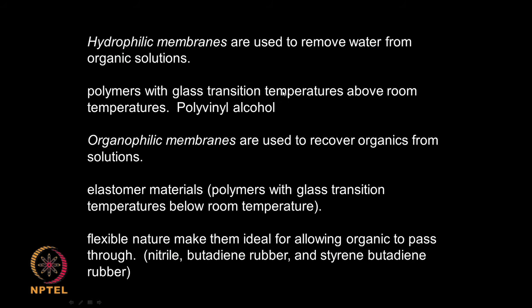Polymers with glass transition temperature above room temperature, like polyvinyl alcohol. Organophilic membranes are used to recover organics, obvious, right. If it is an organic, then you like an organophilic membrane, like elastomeric materials, polymers with glass transition temperatures below room temperature.